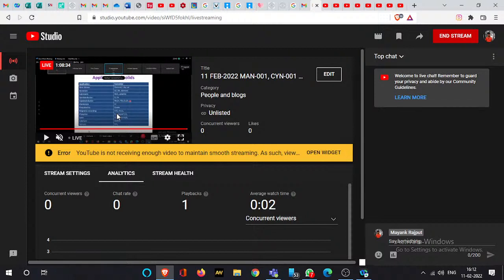If you want to generate a huge magnetic field using an electromagnet, then obviously you have to provide a lot of current to the coil. The coil you are making will have some definite resistance. If that coil is made out of superconductor, you can push so much current and generate a very high magnetic field strength.